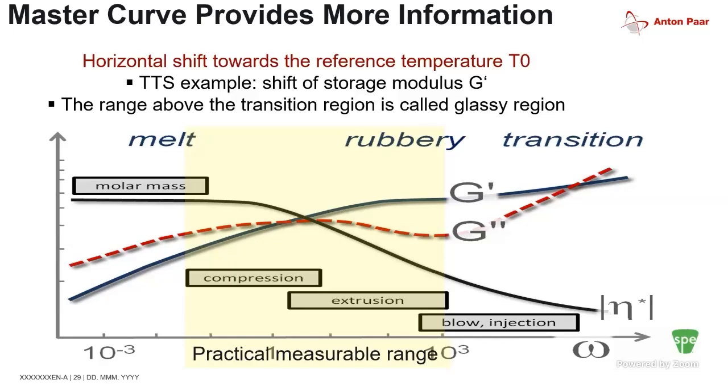Now, certain things you have to do with the data is to prove through what's called the Cox-Merz rule. You would look at your frequency sweep data, compare it to rotational data, and if the complex viscosity and the rotational data overlay each other, this indicates that your material response behavior should technically hold in that case. And there are ways of looking at it so that you should see a fairly easily shifting behavior. But again, it doesn't hold for every material, so you have to look at it on a case-by-case basis.